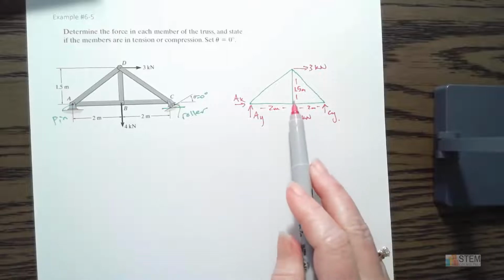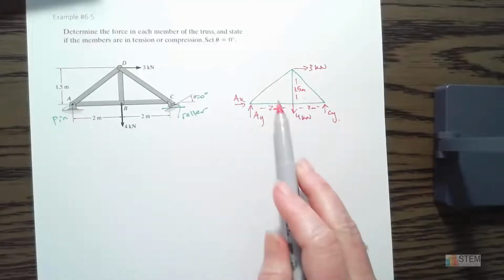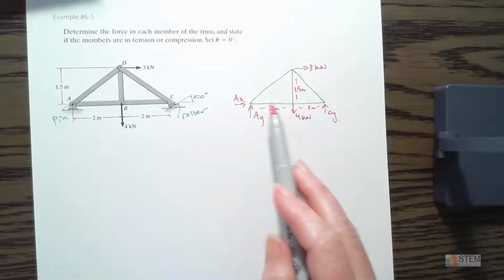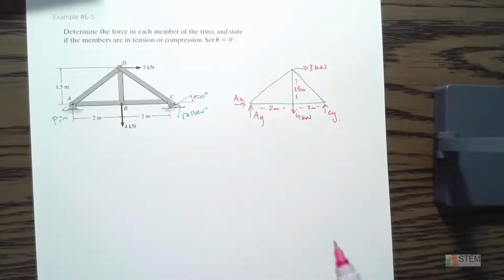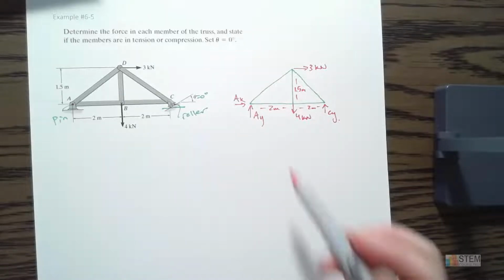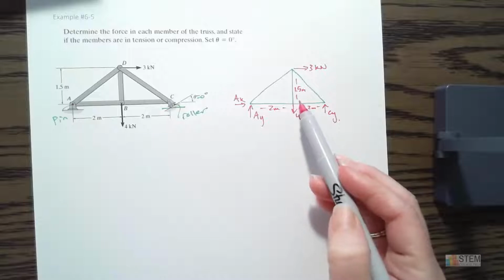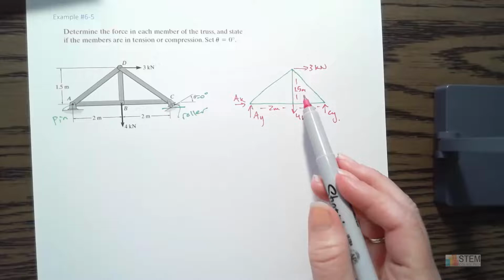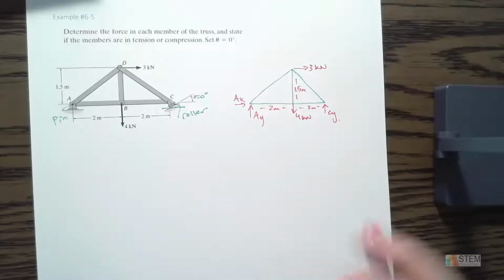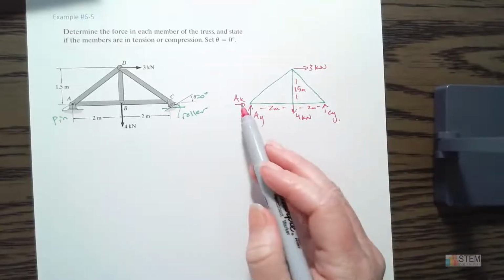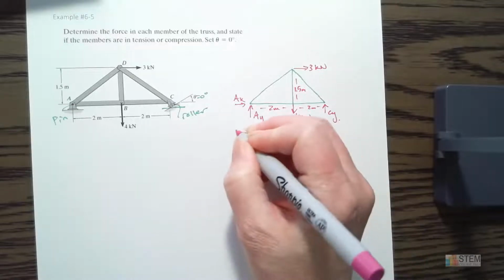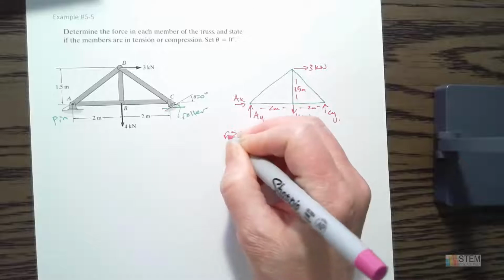Now notice that we don't have any of the forces inside of the members listed here. The reason for that is these members are all connected together, so we've got the equal and opposite reactions caused by Newton's third law. All of those forces cancel each other out, and that's why we don't have the forces for the members in this diagram, because they're all connected together. Now notice we've got 3 unknowns and 3 equilibrium equations, so we can go ahead and start solving those.